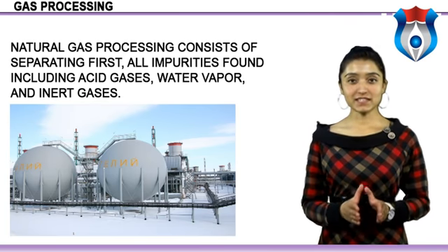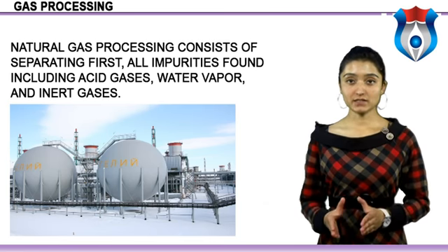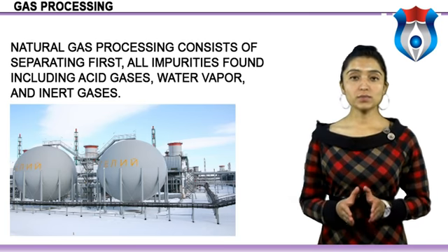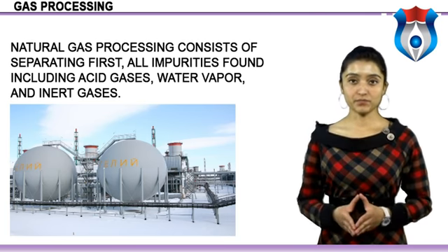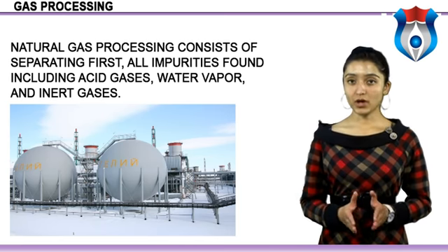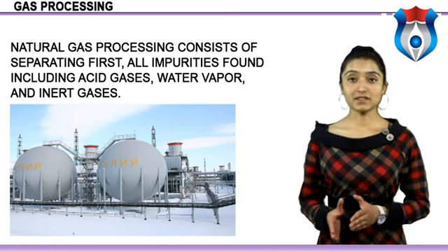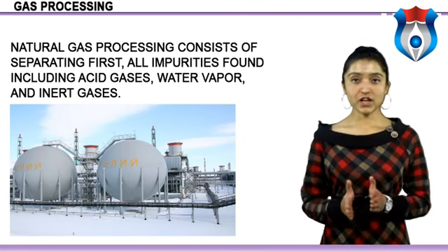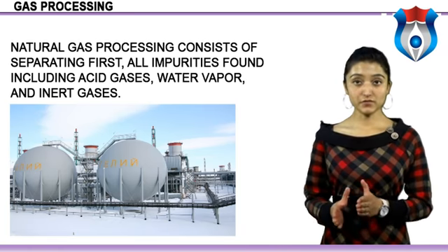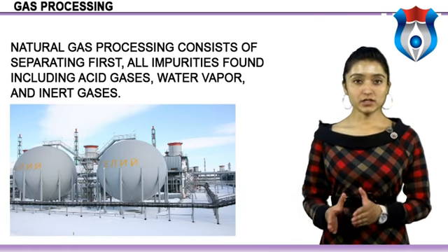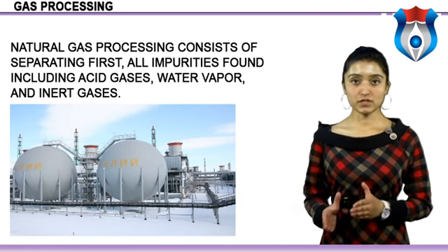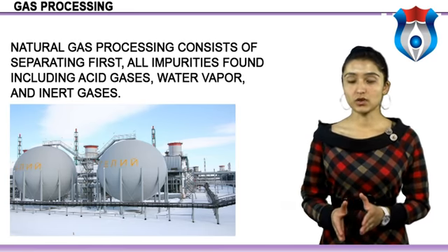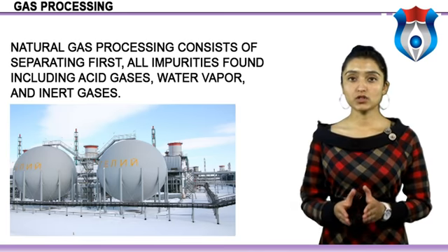Gas processing is the second and most important stage, concerned with the recovery and extraction of NGL from natural gas, followed by fractionation to separate components. Modern gas processing plants use a cryogenic low temperature distillation process based on the expansion of the gas through a turbo expander. A fractionation column called a demethanizer follows. Methane, the residue gas, and NGL are the products from this column. Fractionation of NGL requires the use of a number of distillation columns for the separation into the desired components and products.